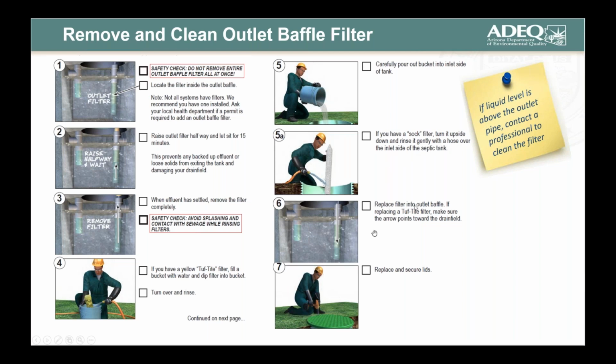Replace the filter into the outlet baffle. If replacing a Tough Tight filter, make sure the arrow points toward the drain field. Then replace and secure the lids.